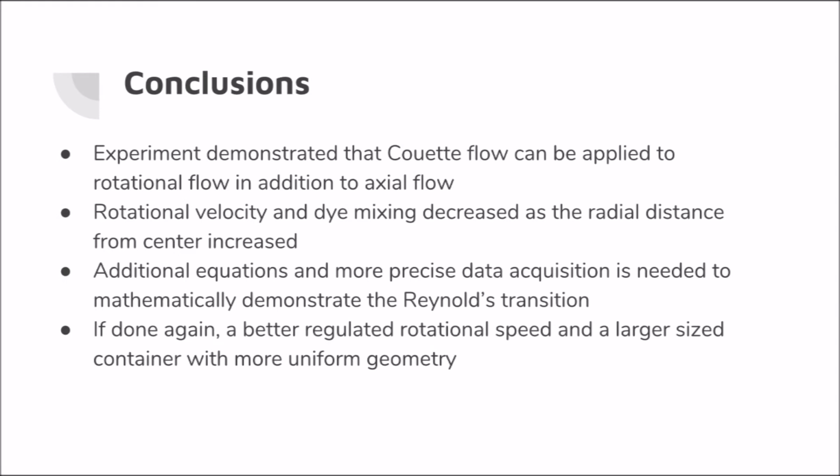In conclusion, our experiment demonstrated that Couette flow can be applied to rotational flow in addition to axial flow. We found that the rotational velocity and dye mixing decreased as the radial distance from the center increased. Additional equations and more precise data acquisition, such as better regulated rotational speed and a larger sized container with more uniform geometry, would be needed to mathematically demonstrate the Reynolds transition.